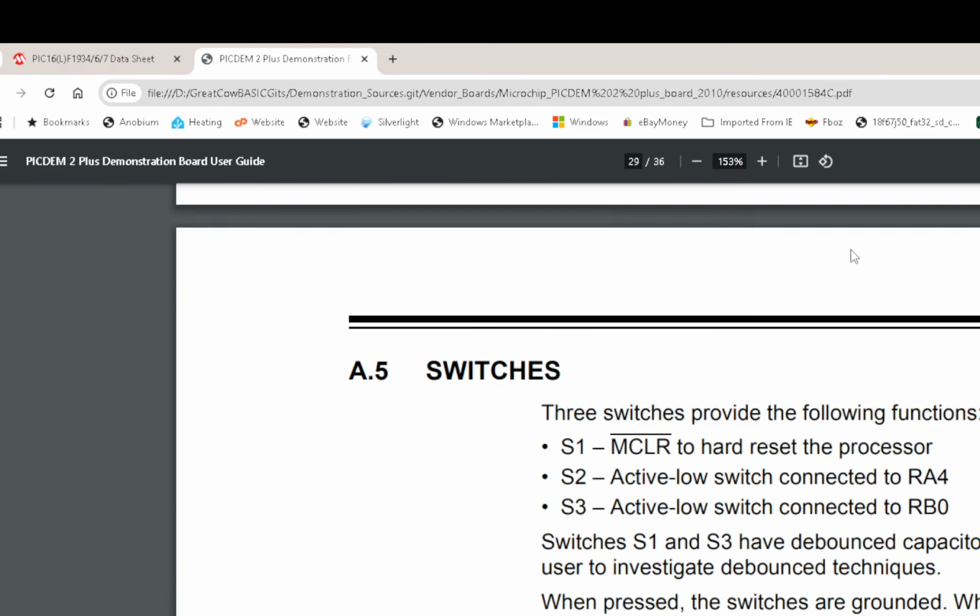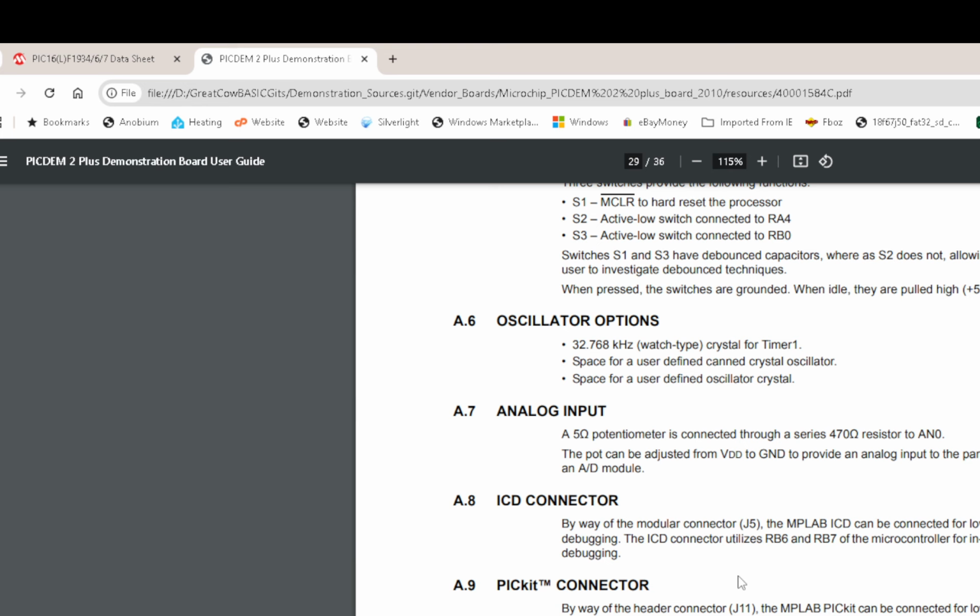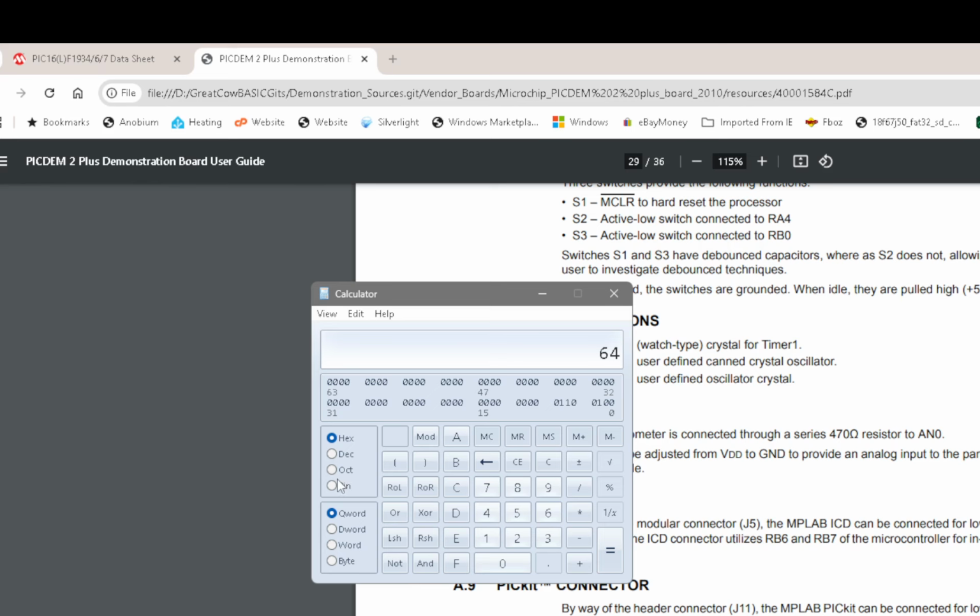Oh, wait a minute, look. It says 256. I'm just doing a search on it. It just says here it's connected to the bus. There you go. Oh, here we go. Look, it has an address. That's the temperature sensor. Let's look at that in a calculator. Now, it's address 4D, and that's a 7-bit address. So if you just shift that to the left, or multiply it by 2, the address is 9A, and that is quite correct. So we used 8-bit addresses, and that is documented as a 7-bit address.